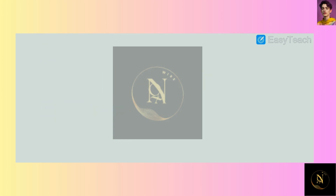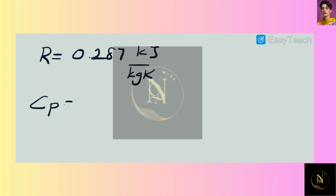So first thing we're going to do is find the properties of our gas. We know our gas is air, so the gas constant is going to be 0.287 kilojoules per kilogram Kelvin. And we're also going to see that our specific heat for constant pressure, Cp, is going to be 1.005 kilojoules per kilogram Kelvin. And this is a quantity that pertains to the Cp at room temperature.